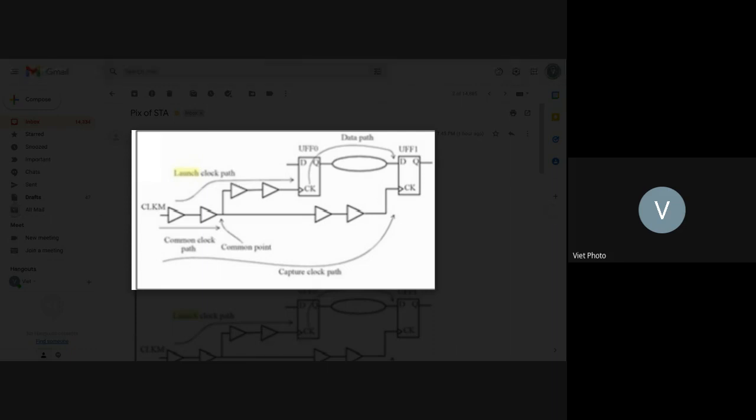Then the CTS, that means the clock tree synthesis, will have to try to balance that logic-wise first. So if it sits right here, then it would not even need a buffer, because the flop sits right here. But because the path goes from here to the next flop here, right? It has, let's say in this case, 2. Then it has to add 2 cells here, so that the number of cells going to the flop will be equal.